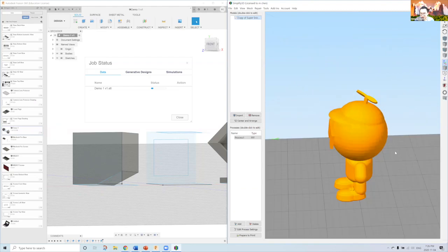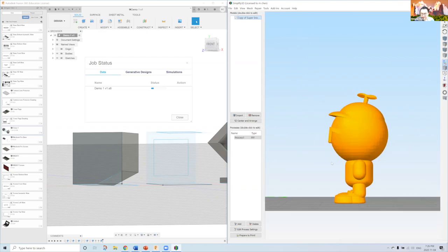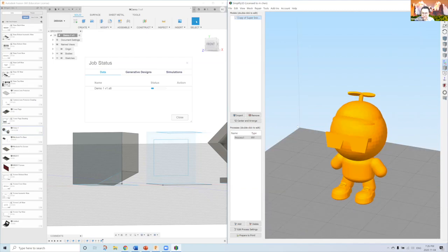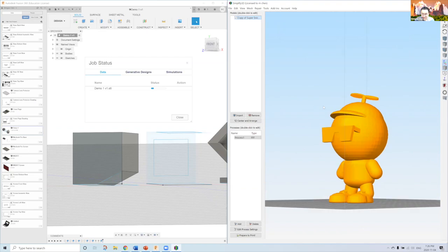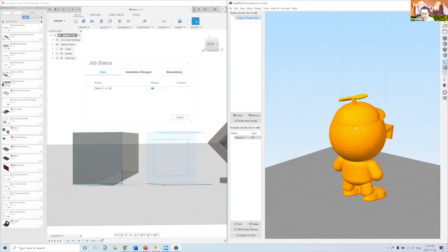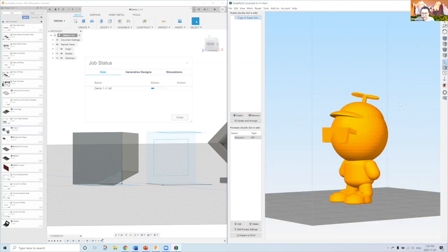So if you had your 3D printer print this directly, you'll have quite a bit of problems managing some of these components, just printing in thin air. So this model in particular, there's actually not a lot of better ways you can orient it considering how it's designed. So what you would do in this circumstance, you have to implement supports for the model.